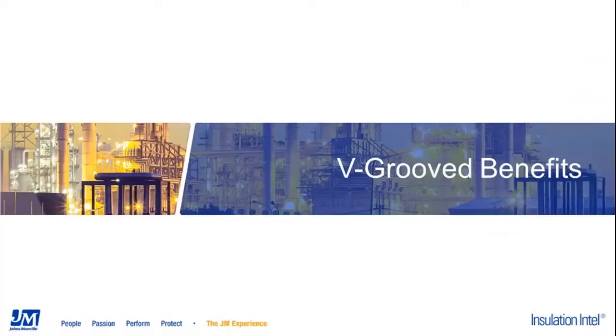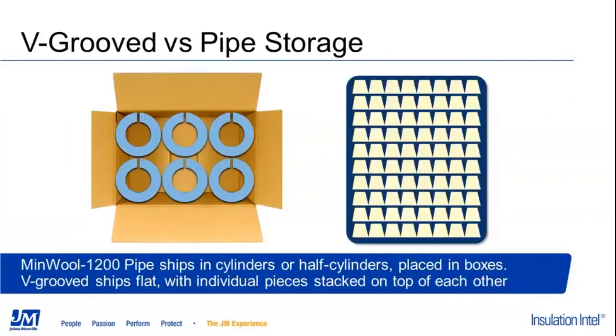So now let's move on and take a look at the V-groove portions of the mineral wool product family. I had touched on this a little bit at the beginning in the introduction when we were looking at the different configurations available. And this slide gives you a very good graphical representation of the big difference between molded or mandrel wound pipe insulation versus V-groove pipe insulation. On the left side, you see the molded or mandrel wound material. It does ship in the round format, so you have a limited amount of material in a box, whereas the equivalent V-groove material, since it ships flat, you can get a whole lot more material in the same or less packaging volume or space on your warehouse floor.